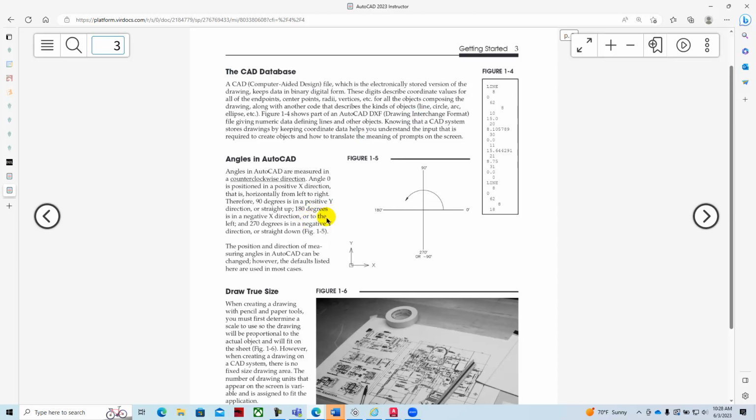The book is an excellent tool for organization, and I believe Al and I have the video set up so that you can see how those concepts are applied using the computer system. And so angles in AutoCAD, 0 is horizontal at the 3 o'clock, 90 would be vertical at 12, 180, if we were to put a clock face on this, would be at 9 o'clock, and then 270. And so these are our angles that we'll work with as we draw lines at specific angles. Like you want a 1-inch line at a 45-degree angle, you would have a line like that.